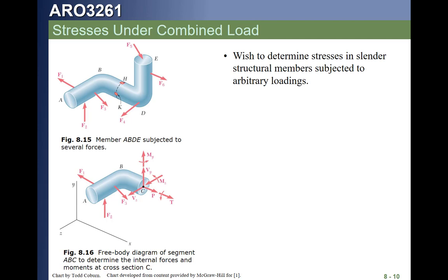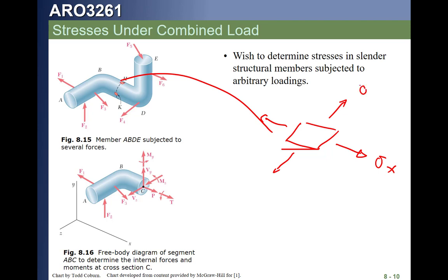And in the same way, at point Z, we're going to get normal stresses and shear stresses. Once we have all the stresses on the little elements, what that means is if we pull out point H, we're going to have a little element lying like this, and when we do the P over A plus MC over I, we're going to get a little stress like this on the thing, and potentially a little stress like this, and we're going to get shear stresses that are acting like this or in the opposite direction.